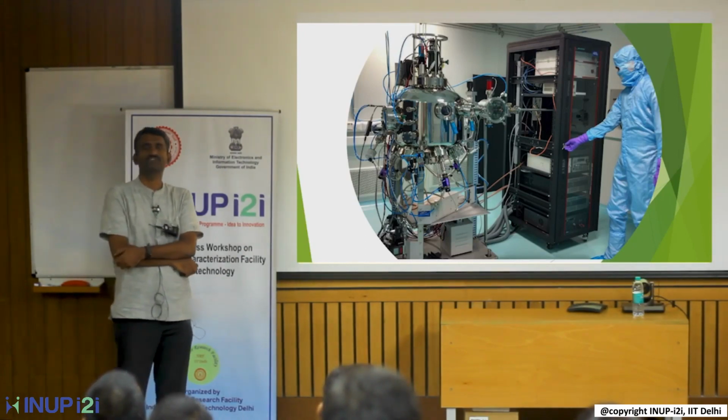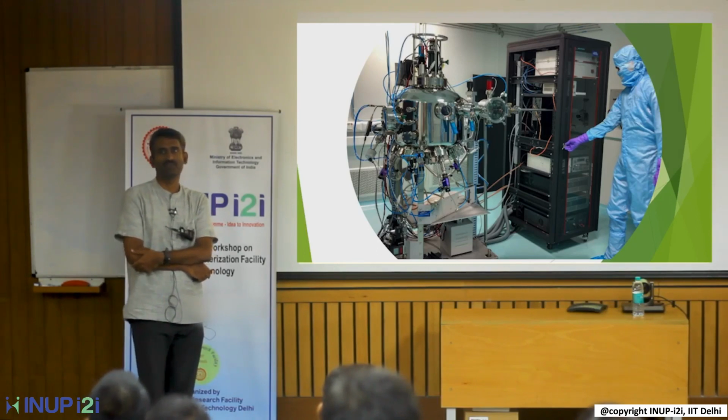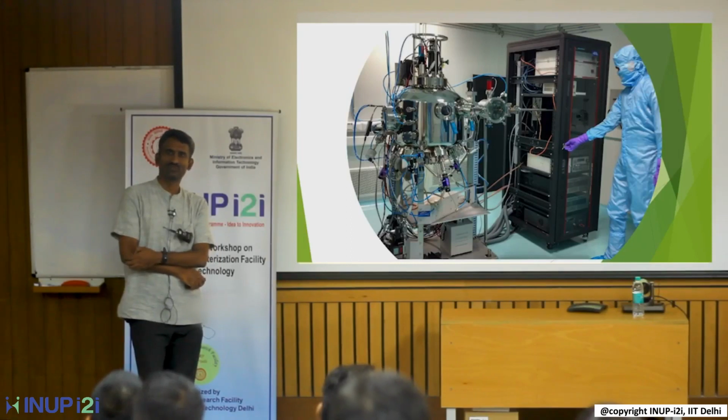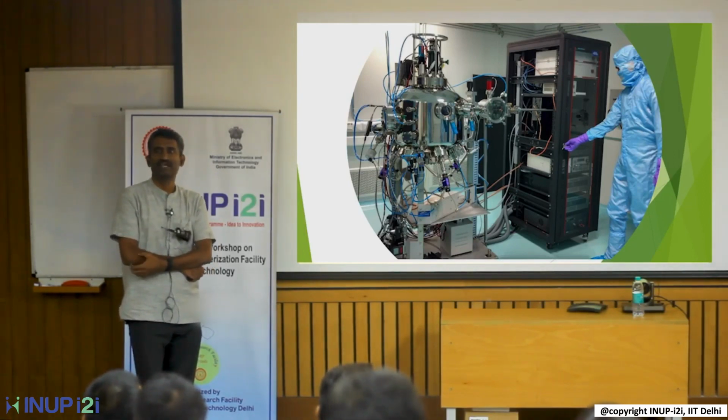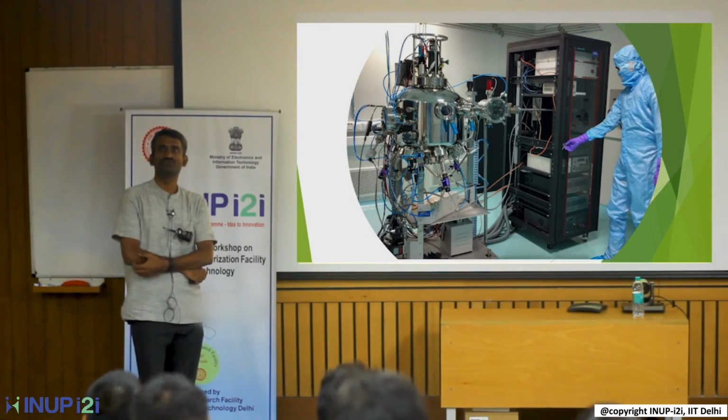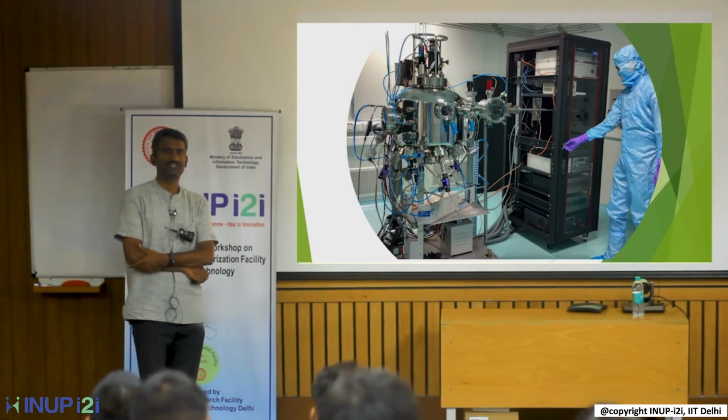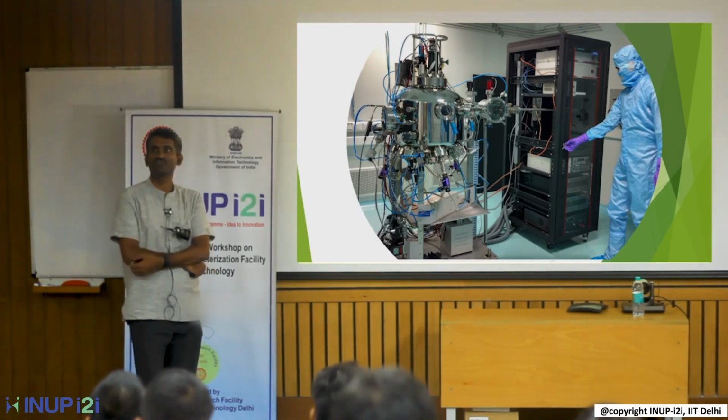The UHV system can be used for various applications because of the reproducibility and the material properties. The initial vacuum is very important. In papers, and even experimentally, we see that the purity of the argon source gas is also very important, along with the base vacuum and the vacuum conditions during deposition.